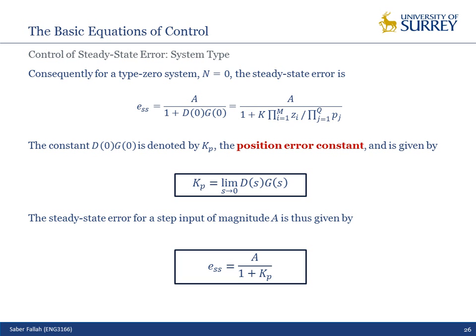or settling time or rise time of the system. The proportional controller works very well, but the only thing is the steady state error is not 0. It changed the steady state error of the system, increased the steady state error of the system. By adding an integrator, as in a PI controller, you will have steady state error equal to 0 or lower steady state error. That's why we are talking about this system. Okay? To have an idea of why we need to use PID, PD controllers.